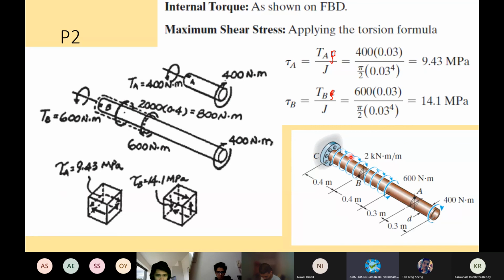Okay, see here at this point, all is one by one, right? You're asked to find the stress at A and B, right? For this, you need the torque. What are the moments acting on it, so that you can conveniently substitute here to solve it. How much is the torque here? If no torque moment is given, forces are given, you have to resolve and get the moments, isn't it? Torque is nothing but the moment in Newton meter for the given loading. In this case, torque is directly given, alright?